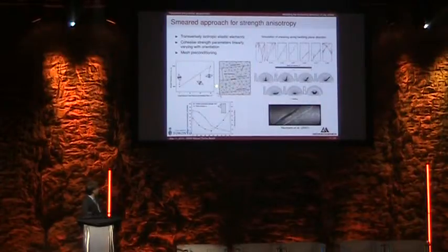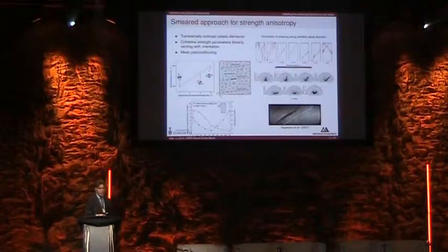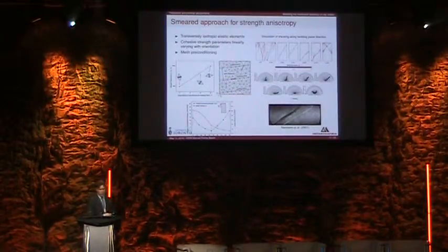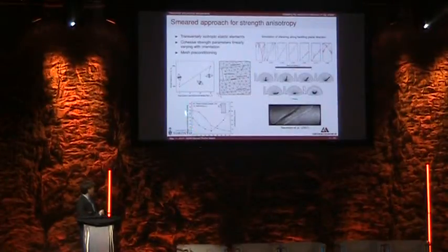So essentially we vary the cohesive strength parameters of the rock as a function of the orientation of this crack element with respect to the bedding. In this case, we assume minimum strength properties when you're on the bedding plane, maximum strength properties when you're perpendicular to them, and a linear relationship in between. And we were able to calibrate the model to reproduce again the U-shaped strength response.